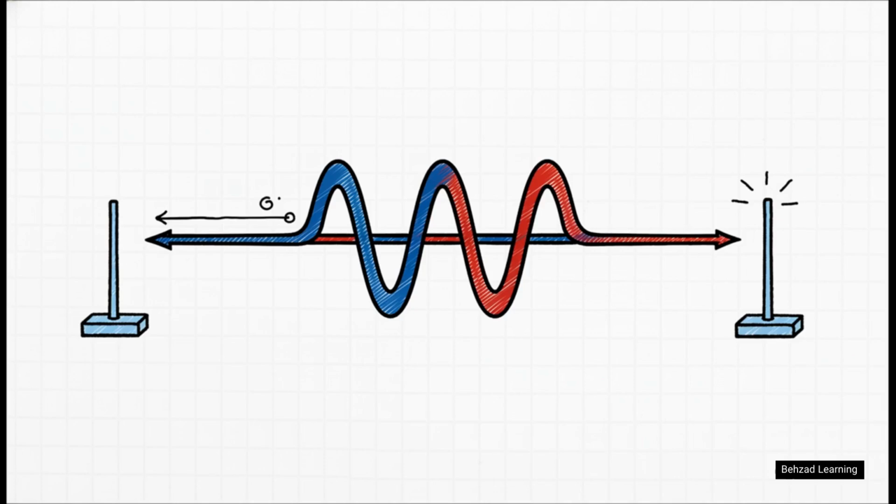That movement, that actual transfer of energy, is exactly how a signal travels. So the absolute crucial point here is that your Wi-Fi transmitter acts exactly like that person shaking the rope. It sends an alternating electrical current into a section of wire, which is the antenna. This action creates electric and magnetic fields that travel outward together at right angles. These waves cycle up and down, and the speed at which they cycle is called the frequency, which we measure in hertz. The receiver's antenna then catches these moving fields and converts them right back into the data you're downloading.